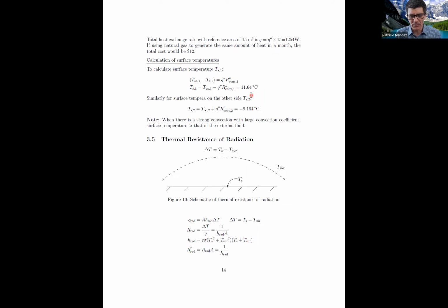But if I'm in my Argentinian house in Canada, my walls would be at 11 degrees. So the temperature of surroundings is not 20 degrees. The temperature of my surroundings would be 11 degrees, and I would be losing heat by radiation with a temperature difference between my 33 degrees of skin and 11 degrees on the wall, not 20.